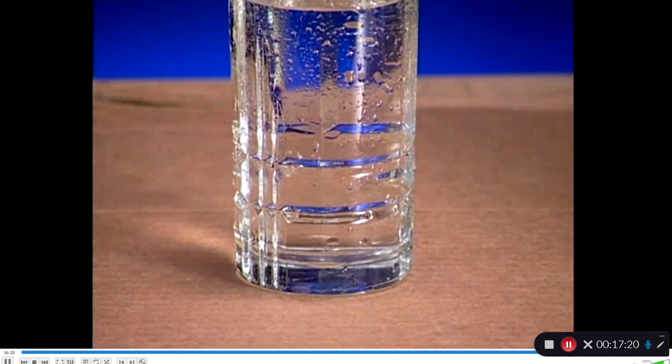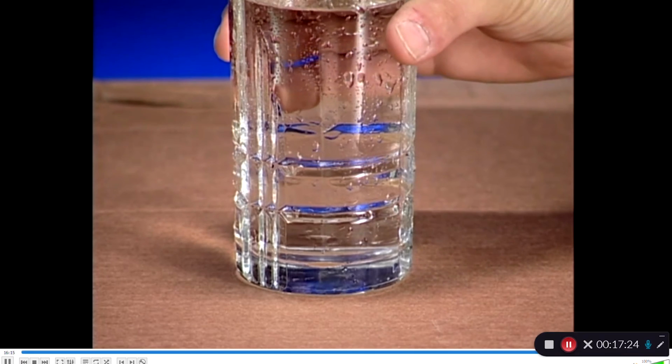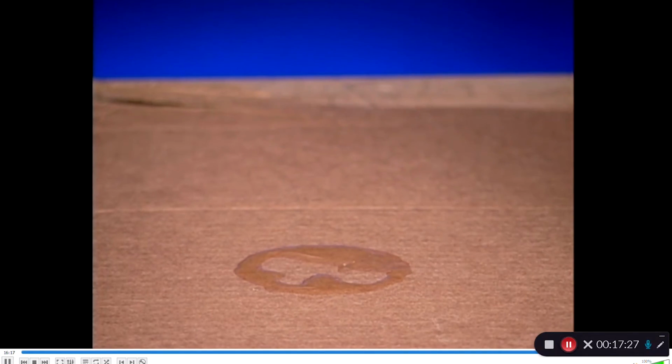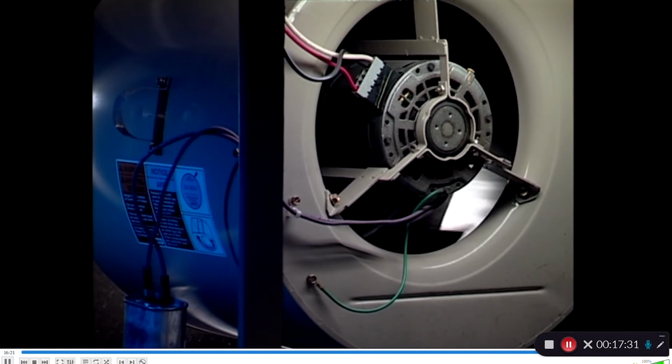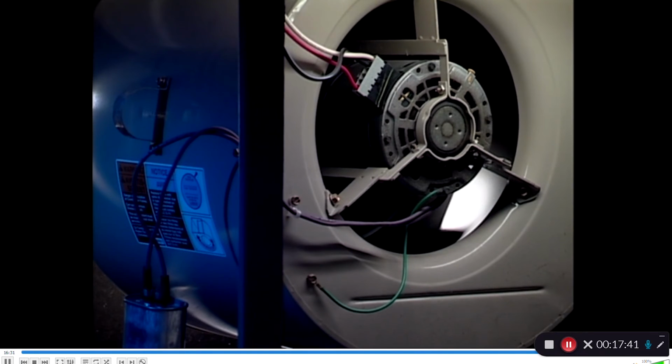Another important air property is the dew point temperature. This is the temperature at which moisture begins to condense out of the air. Air can be dehumidified by passing it over a surface that is below the dew point temperature of the air. One example of this is the evaporator in an air conditioning system, which cools the air as well as dehumidifies the air.